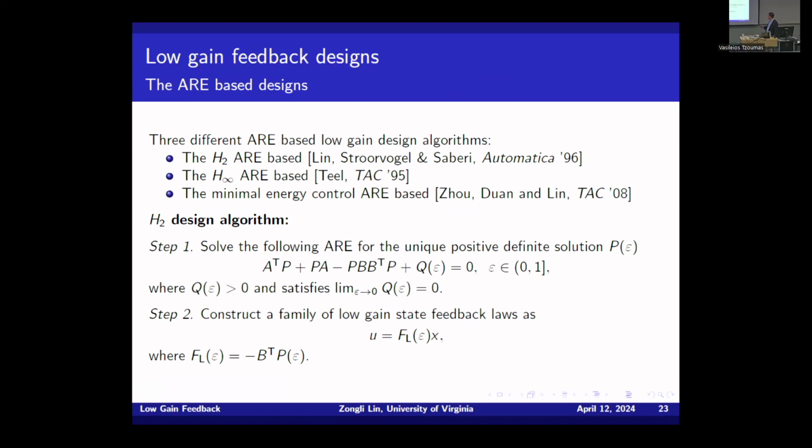And after that, there are a few methods that have been developed, but you get similar properties. The one is H2 ARE based, basically the LQR Riccati equation, but you make the Q matrix epsilon dependent. And as Q goes to 0, we have similar properties. About the same time, Andy Teel came up with the H infinity ARE based. And he was able to use H infinity to gain some additional robustness in the input channel.